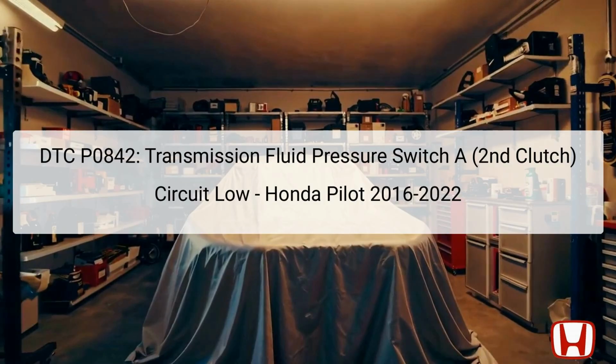In the event of a malfunction, the PCM will engage a fail-safe mode, restricting the transmission to only second or fifth gear to prevent further damage. It's crucial to address this error promptly, as continued driving under these conditions could lead to more extensive transmission repairs.